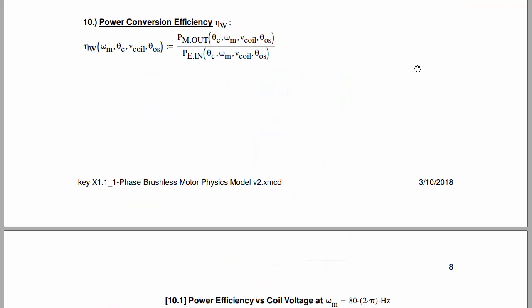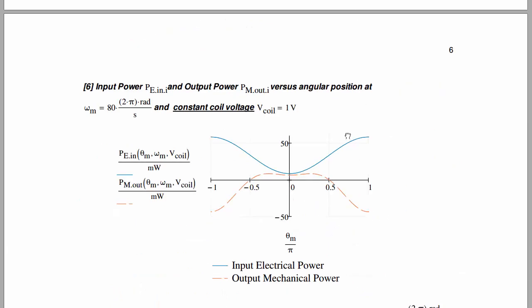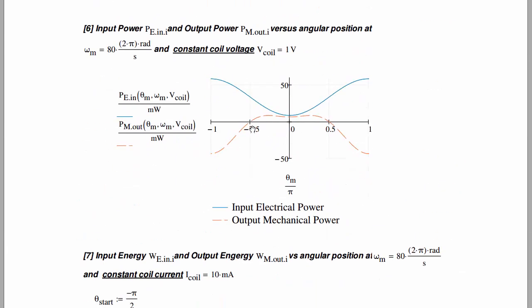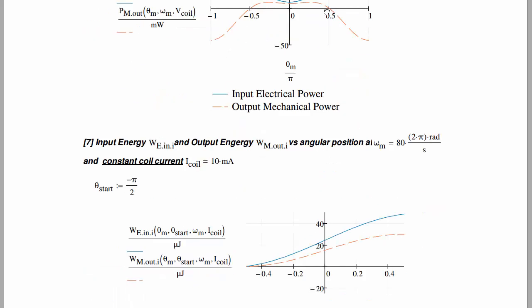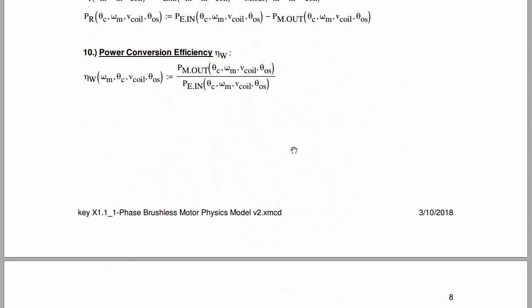Now pi, what it means is that we are conducting from -90 to +90. It is centered about 0. So we're going to conduct over the full maximum range for which we can deliver power, even though it's reduced, it's vanishing here at the edges. We're going to energize the coil over the full -90 to +90 as our starting point.